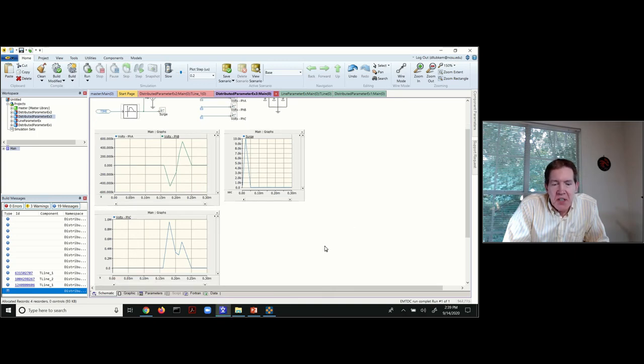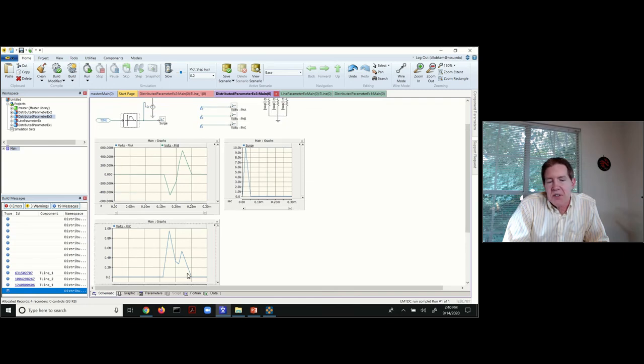And basically what I see on the impacted phase is this really huge voltage. And this is jumping up to about a megavolt. All right, so what's happening in this case, if I'm injecting this current, maybe this current doesn't seem like that high a value, but then you have to multiply that by the surge impedance to get the voltage. And so that current injection translates into a really high voltage.